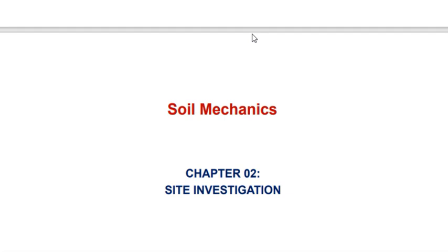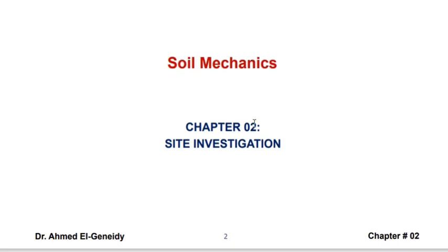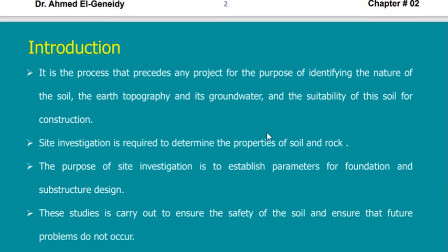This is very good because now I know the depth of the layer and I know the properties of this layer, so I know everything. Followed by another layer with a depth of, say, 3 meters with clay with a C value of so and so. So now I changed what I see and what I do not see into numbers that I can use in my design later. So this is exactly what site investigation is.